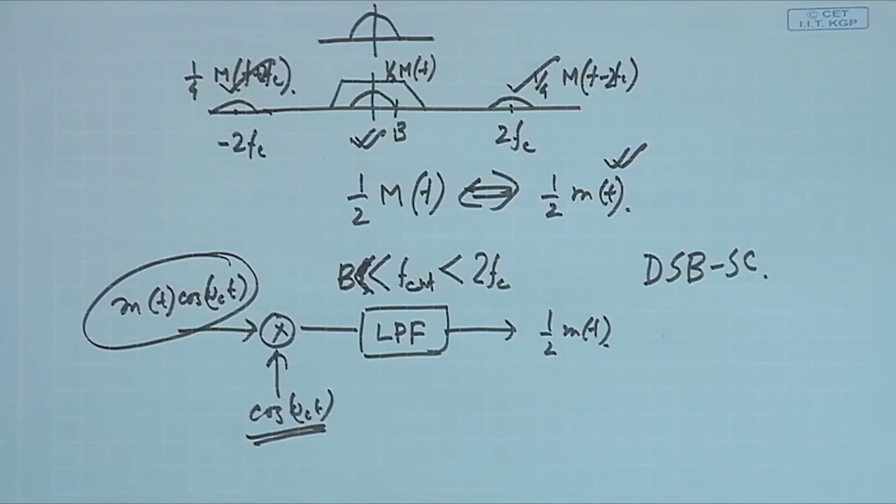That is why short range radio communication people have used SSB, DSB, double sideband suppressed carrier, this particular modulation technique that we are discussing. So whenever we have one-to-one short range radio communication, which is not broadcasting in nature, we can employ this kind of technique.